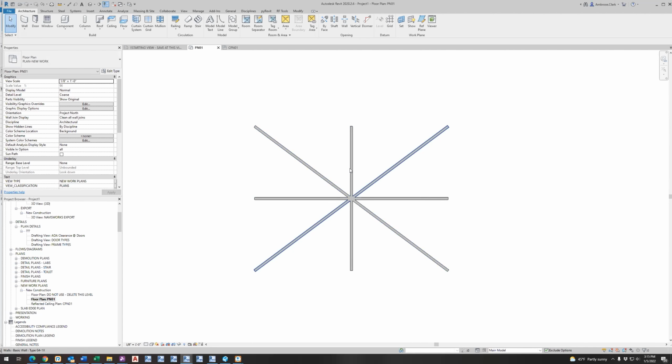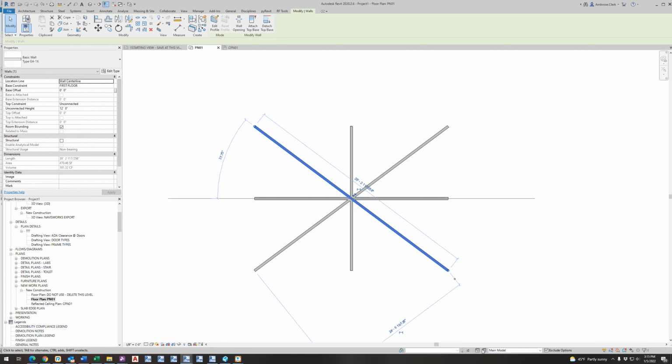So once you model things, and I don't know if you are going to be modeling existing conditions or you know what you want to do, but once you have stuff modeled, you can select something, and right next to that design option button, there's one called Add to Set. You click that, it brings this up. You choose your option set from the dropdown, and you choose your options. You can add them to multiple options.